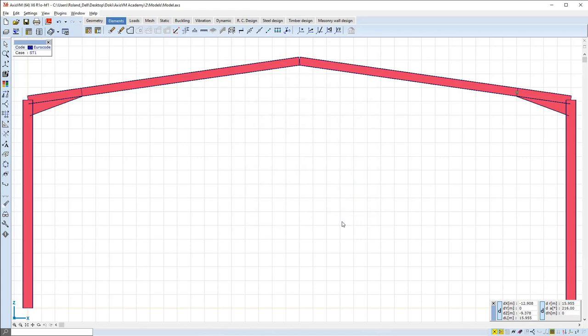However, we are working on a 2D frame. Lateral support effect of the secondary load-bearing system, like the purlins, are important. The supports they provide can automatically be taken into account during stability calculations using the AutoMCR method, and their effect is important during buckling analysis as well to get the proper forms of stability losses and their corresponding eigenvalues.